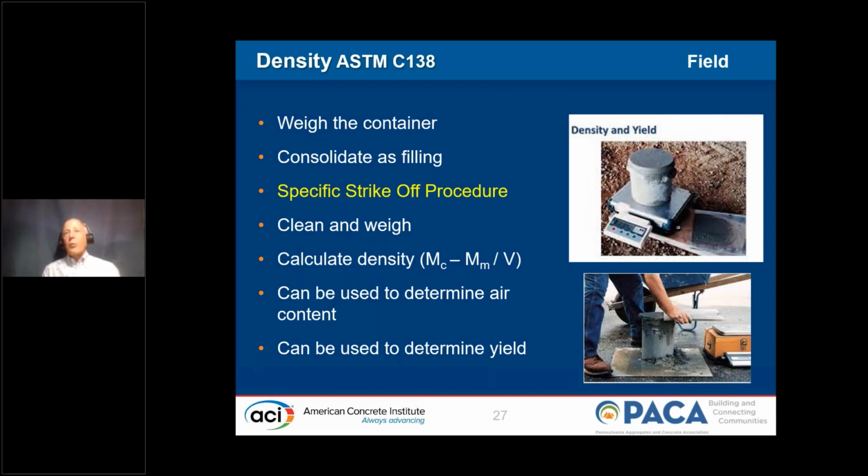But the second most important thing we can get from that number, once we have our unit weight, is the yield. We can tell exactly how many yards of concrete were in that concrete truck.